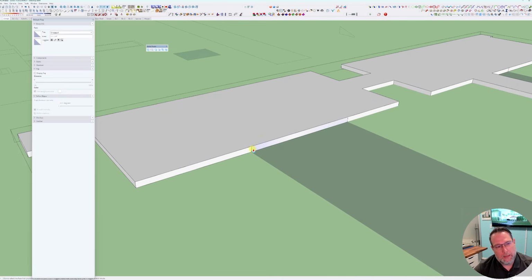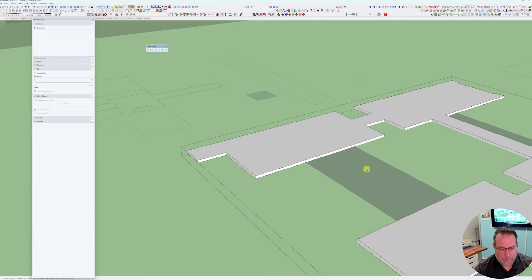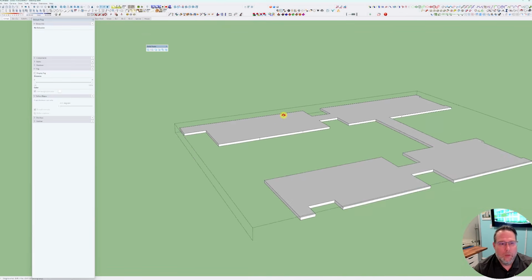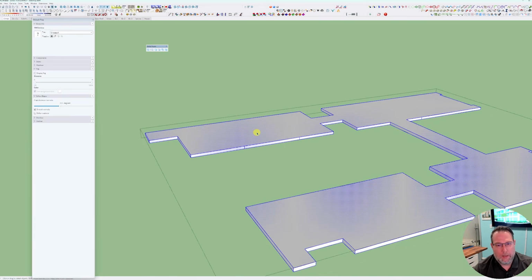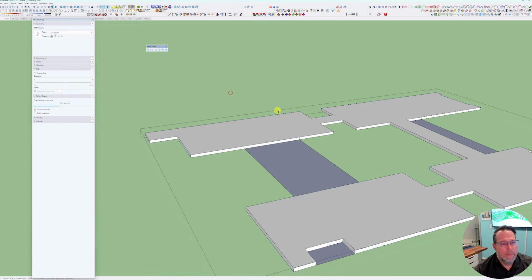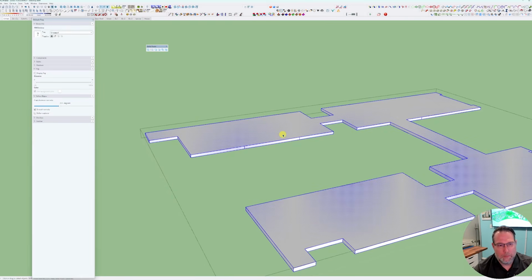So you see these lines right here were drawn because the overall line was split due to this porch piece being here. Well, what's a quick way we can get rid of that? We've talked about it. If I hit Control A, and then hit my cleanup 3 command, which again I believe is extensions, cleanup 3, or I run my shortcut, you see all those lines instantly go away.